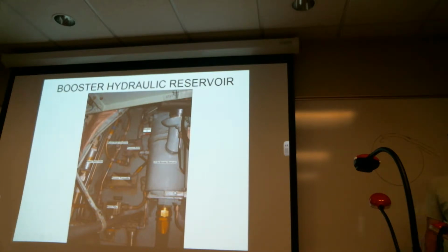Oh, okay, good question. C-130 is kind of different. They've got electric booster pumps that they use before the fluid gets to the engine-driven pumps. That provides the initial push on the fluid. So every aircraft has done a different deal in order to prevent cavitation. The aircraft is pressurized, but they don't use air pressure on the fluid. They just elected to use a separate hydraulic pump to provide the initial push.